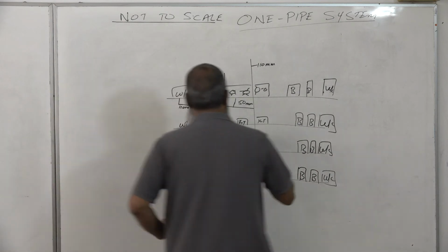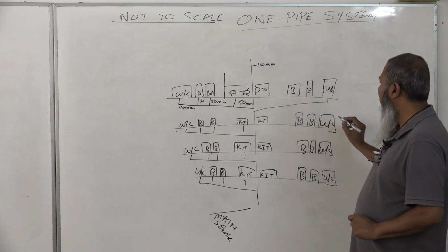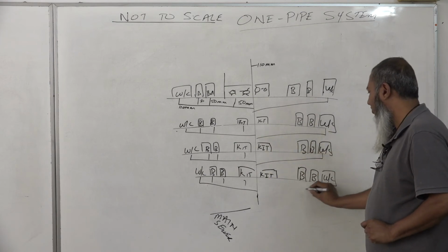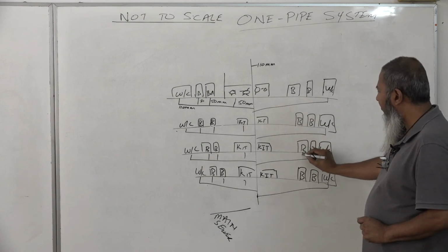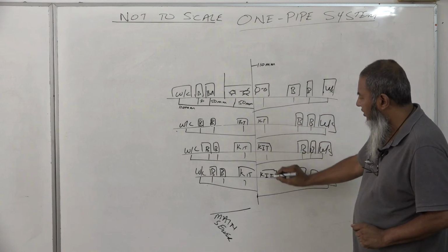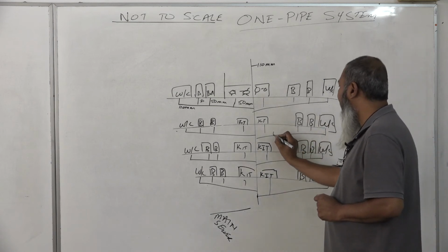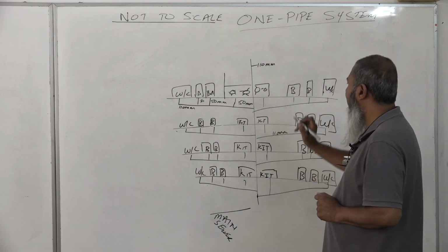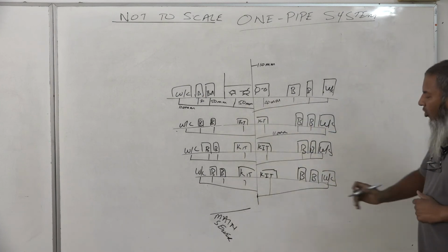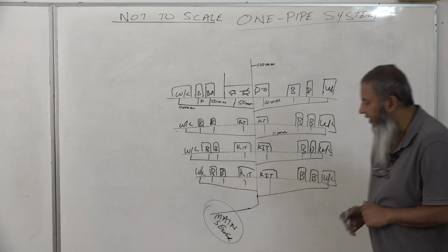The following side comes in again. Water closet, down, water closet, down. Again, bath, basin, kitchen coming in. Now we said this pipe is 110 millimeters. These pipes here are 50 millimeters. Okay, all coming down joined to one common sewer. This is the main sewer which the council provides us with.